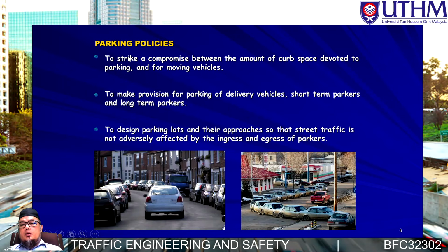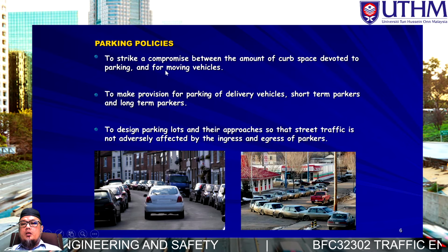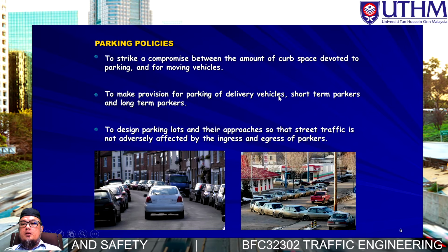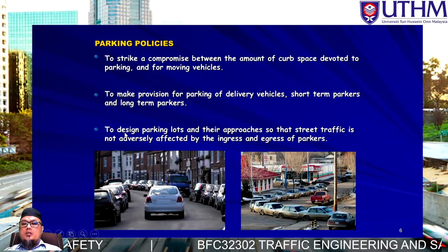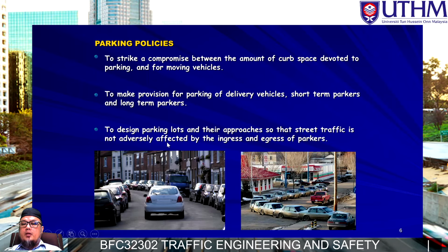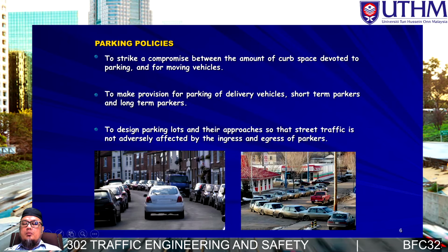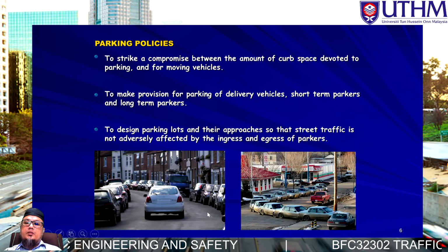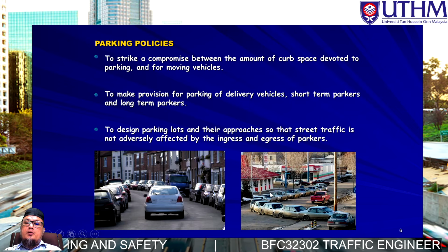Okay, the parking policy should strike a compromise between the amount of curb space devoted to parking and to moving vehicles, make provision for parking of delivery vehicles, short-term parkers and long-term parkers, and design parking lots and their approaches so that street traffic is not adversely affected by the ingress and egress of parkers. So we need to look at this particular situation: there is very limited parking and it's not easy to park the vehicle anywhere.